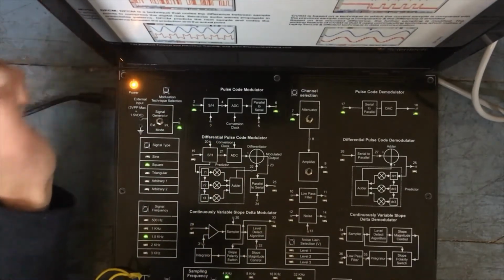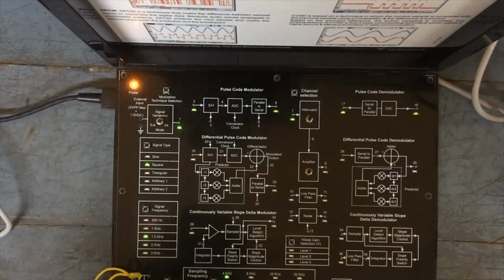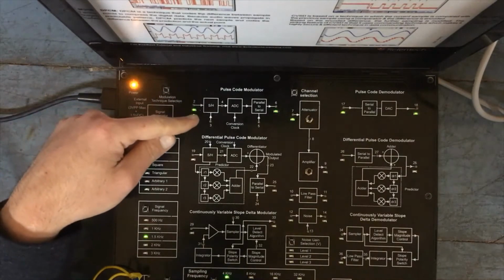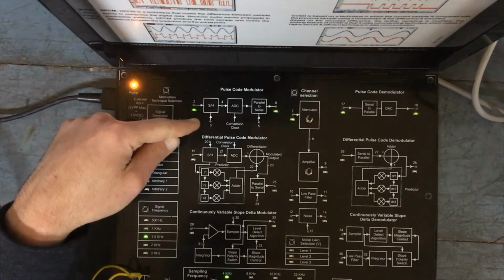If you can see, the sampling frequency can be chosen between four values: 4 kilohertz, 8, 16 or 32, and correspondingly the line speed is the sampling frequency multiplied by 8, that is 32, 64, 128 and 256. So this can be changed, which would change the clock of the sample and hold circuit, essentially how frequently the samples need to be taken, right?